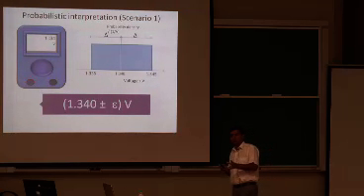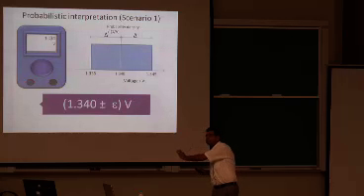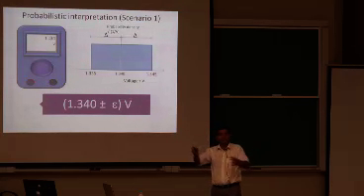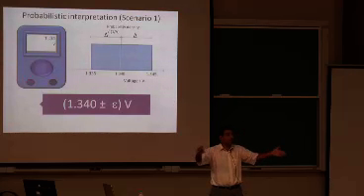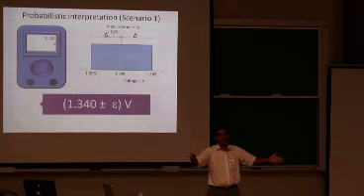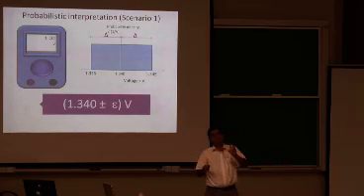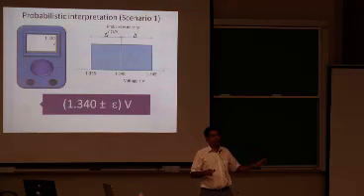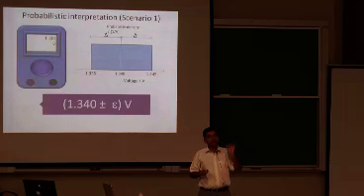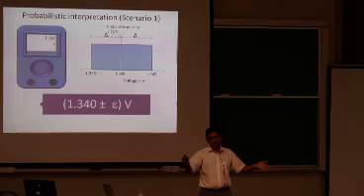So in the GUM approach, even though you're doing a point measurement, still associated with this point measurement is some spread. So you have to specify a spread and you have to talk about the probability distribution function. Now this is just a single reading, so you don't have to perform the experiment a large number of times. Even looking at a single point from the data set, you can specify what the spread of the values could be.